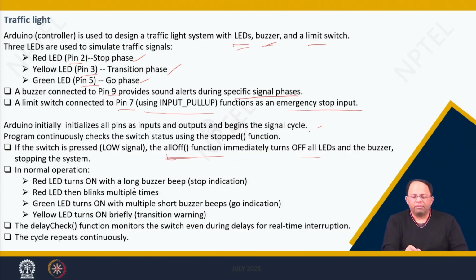But if it is not pressed, that is, it is in normal operation, then the red LED will turn on and it will have a long buzzer beep. Why? Because we would increase the time of that buzzer beep, and this will indicate a stop. Then the red LED blinks several times, then the green LED turns on, and multiple short buzzer beeps will happen. That will say that, okay, you can start, and the green LED and yellow LED turn on briefly in between for transition warning.